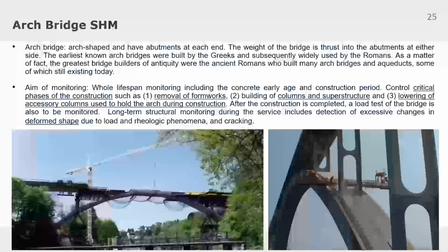So the load test of the bridge has also to be monitored, and during the service, any change in the form shape of the arch due to the load or due to the rheologic phenomena like creep and concrete shrinkage and cracking, well, they have also to be controlled and monitored.